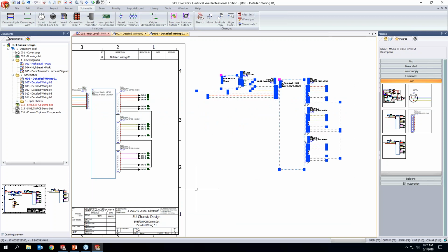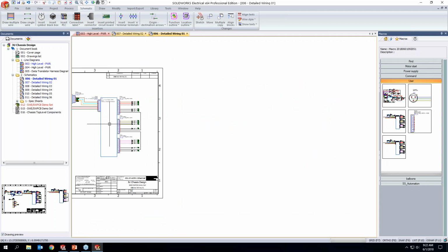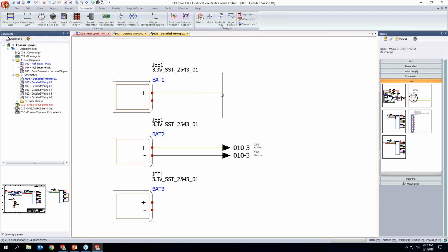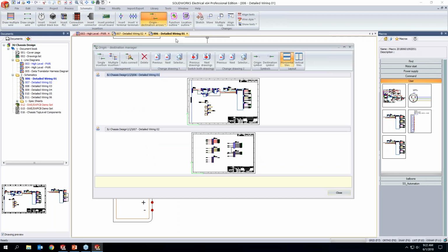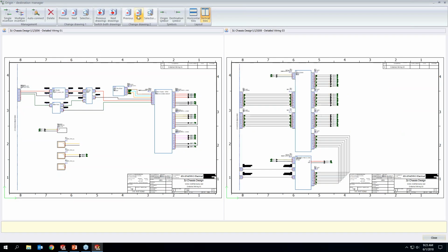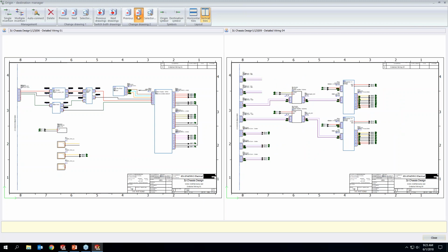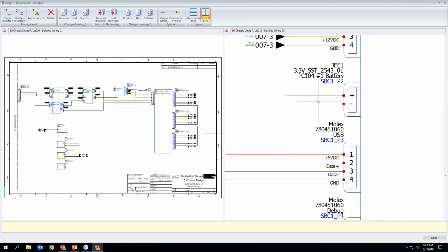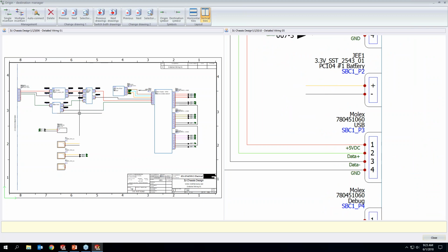So now that we've shown the macro feature, we have to connect a few of our wires, particularly these two, to its opposing end. They're obviously connected to another sheet somewhere. So let's go ahead and find that other sheet first. So we have this tool here called the Origin Destination Arrows Manager. And I'm going to go ahead and find and have two sheets next to each other so I can simply connect these two sheets.